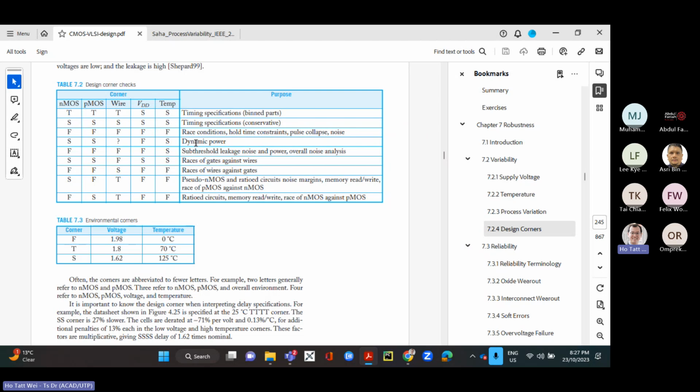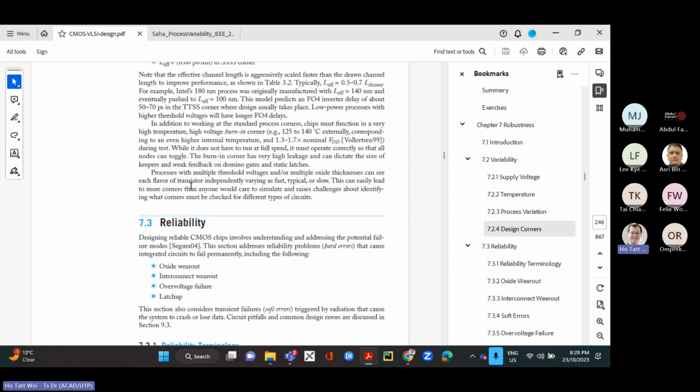And if you are checking the effect of power, then you run the slow corners, but at the fast corner of VDD. This is to look at, let's say, the higher end of dynamic power, and if you're looking at leakage power, then this will be the situation. And there are different combinations if you want to go into more detail to see how your circuit would stand up on some operating corners.